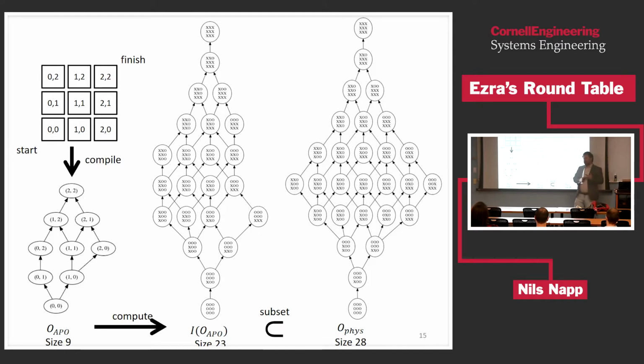But there are other restrictions that are only there because of the way that I program these robots. In particular, I'm using this example and passing it through this assembly order, partial order compiler. Then this is the partial order that I get out of this. I first need to start with 0,0, then I can either do 1,0 or 0,1, but I need to do 1,0 before I can do 1,1. When I fan out, it's pretty easy because everything only has one thing that it depends on, but then I get these joins up here where things come back together. And here, even if I got to this location and this one was assembled, I have to wait. These are the kind of things that make this distributed assembly potentially not super efficient, and the kind of things that we optimize for.